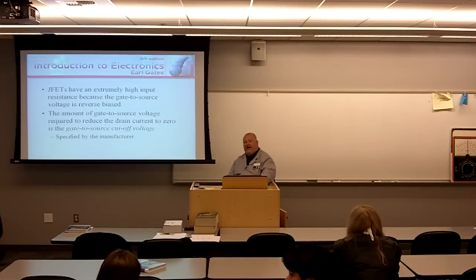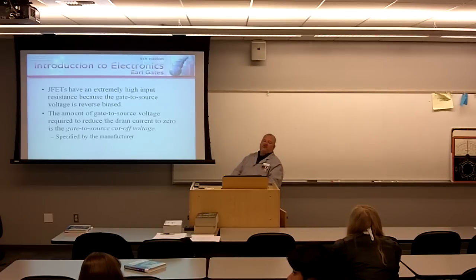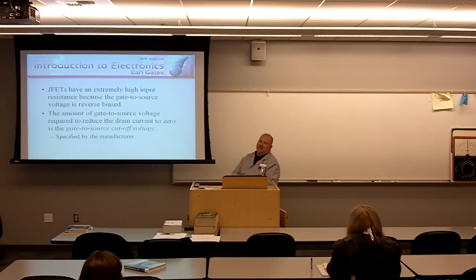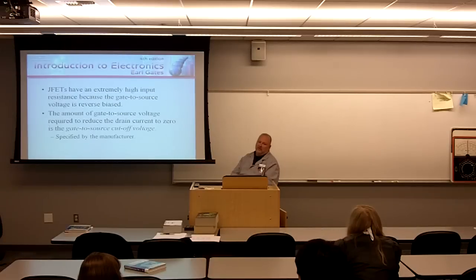JFETs have an extremely high input resistance or impedance because the gate to source voltage is reverse biased. A lot of engineers like this property. High impedance could be a good thing. Is high impedance a good thing? High impedance is a good thing, right?